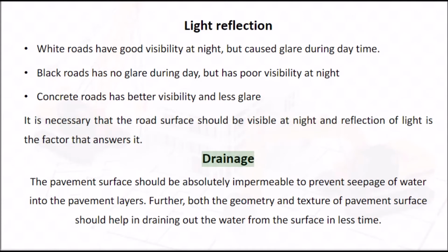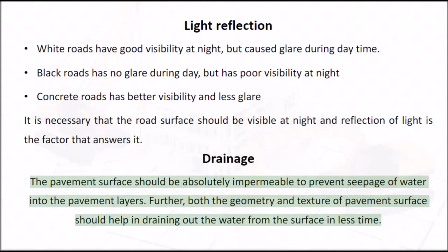Drainage. The pavement surface should be absolutely impermeable to prevent seepage of water into the pavement layers. Further, both the geometry and texture of the pavement surface should help in draining out the water from the surface in less time.